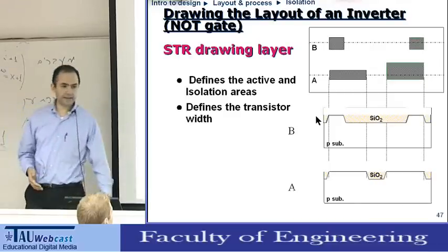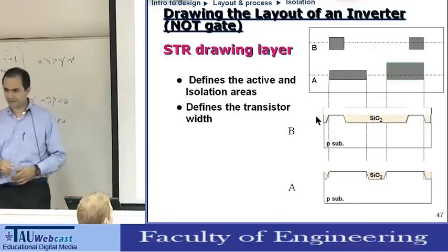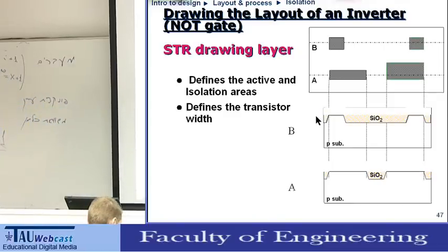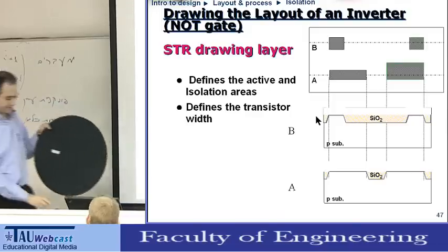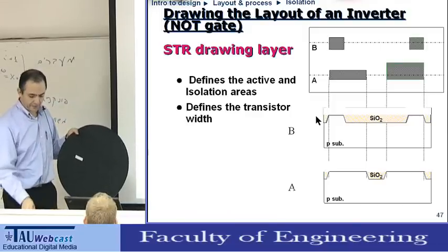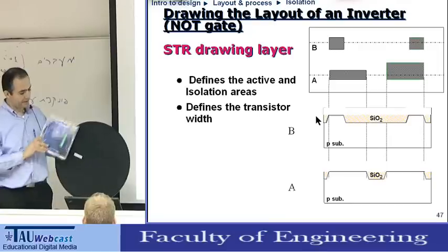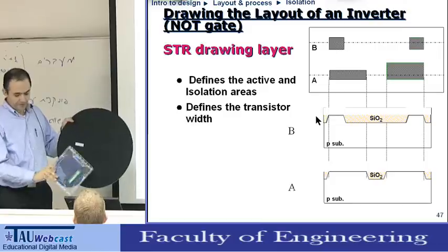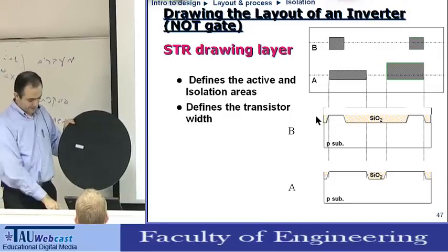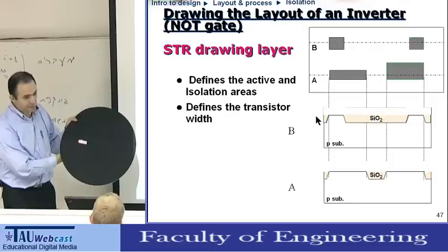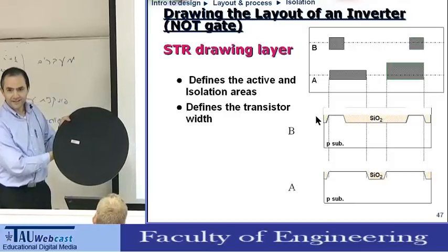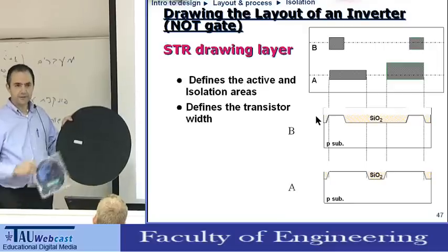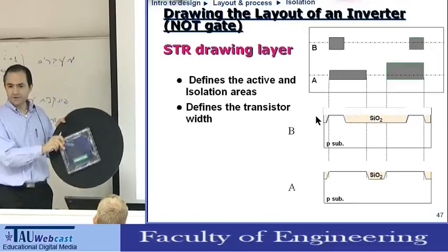So here we can get an endpoint. The real process has a nitride layer that helps us to endpoint. And the way the endpoint is done, this is a polish pad. And the wafer, I won't take it out, but the wafer polishes over the pad, okay? And then you can see there's a window in the pad, and something sticks out of the window. A laser. The laser gets reflected from the wafer when the wafer gets on top of it.